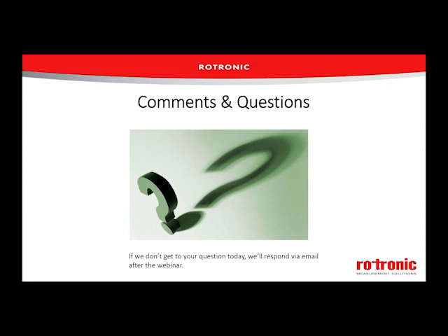With humidity instruments, quite often it's even less than this, a 1-to-1 or a 2-to-1 ratio. And if we called everything out of tolerance, even if the uncertainty band went over our acceptance limit, we'd be able to accept almost nothing as in tolerance. And this isn't unique just to humidity instruments. This applies across the board for all measurement instruments.